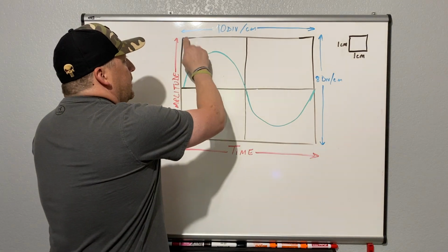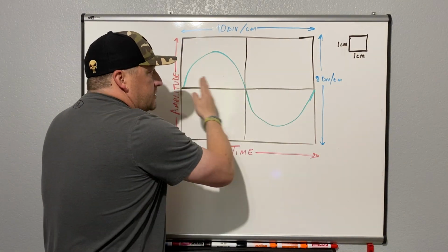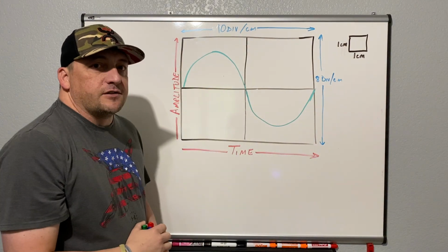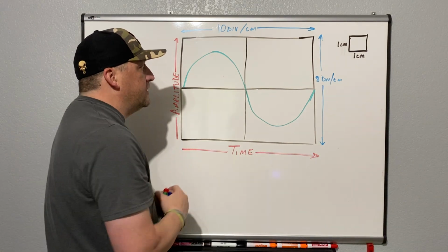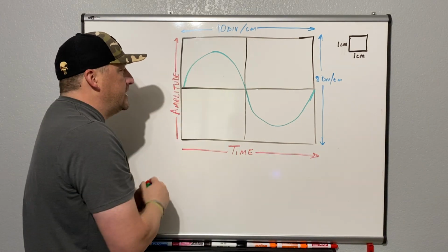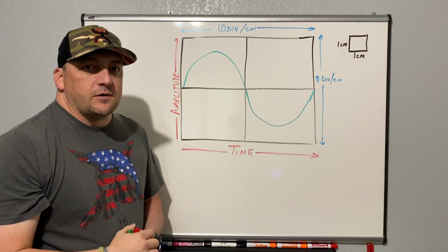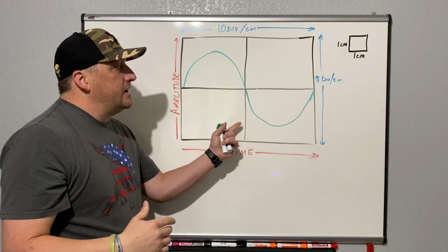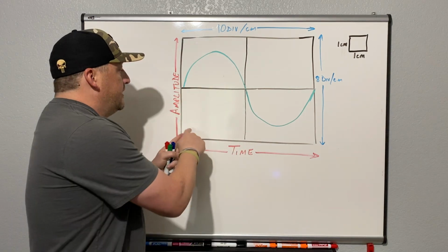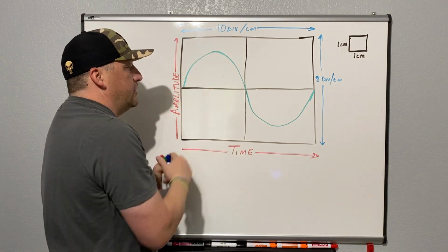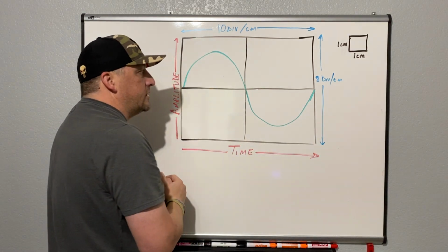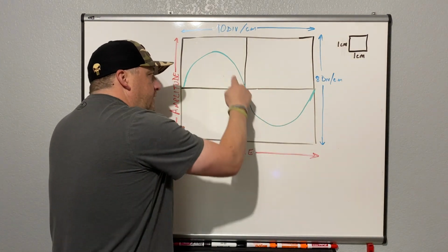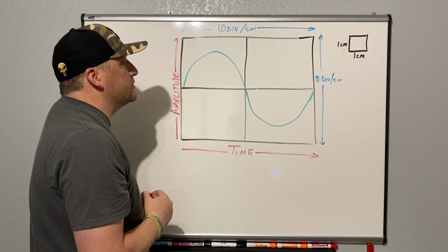Now, across the screen, left to right, that is the time portion of that function, or the time reading of your oscilloscope. The vertical part of the screen is the amplitude, or amount, of your reading. We're going to be reading voltage a lot with this, so this is the amount of voltage that you're reading, and then this is the time it takes for it to complete its cycle, so to speak, or the time of the signal that you're looking at on your screen there.